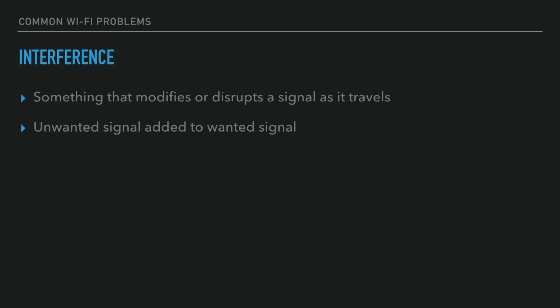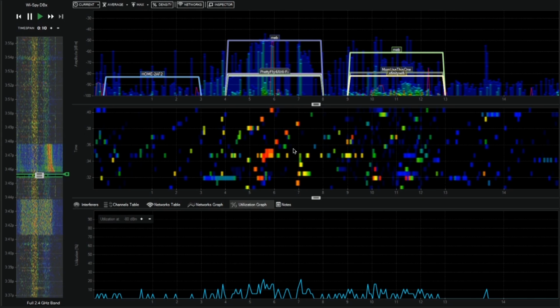I suspect that this is probably due to the fact that 5 gigahertz signals are commonly understood not to travel as far and not to penetrate construction materials as well. 5 gigahertz does not pass through concrete, has more trouble passing through drywall, so on and so forth. So a lot of those consumer device makers out there are going, hey, my baby monitor, I need it to get upstairs, in this house. So I don't want it to transmit in 5 gigahertz. But you've heard us say all this. Wi-Fi people, hey, interference, interference, interference.